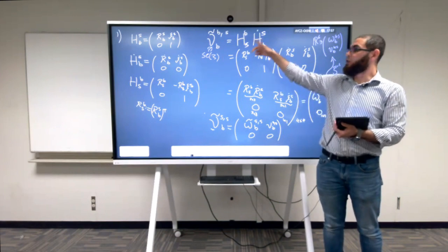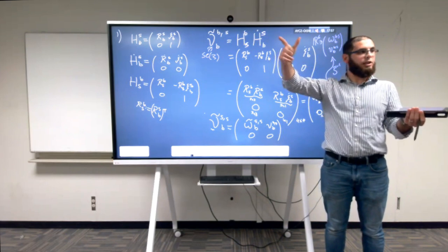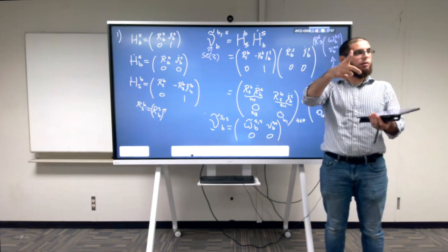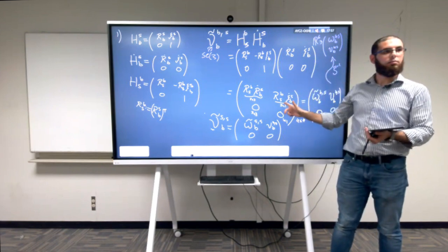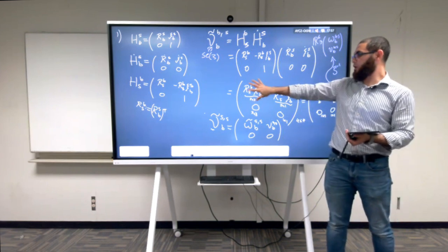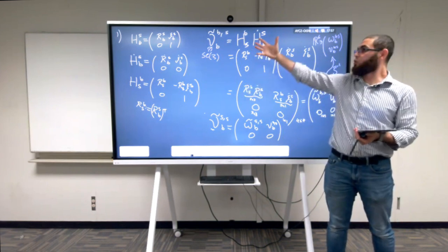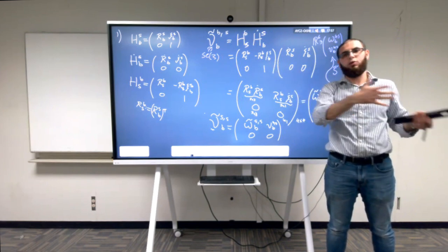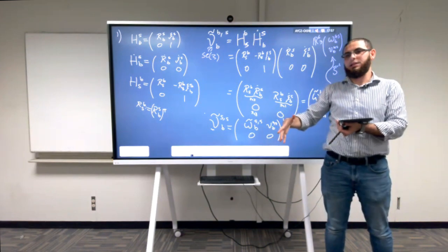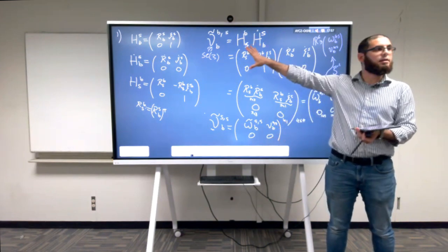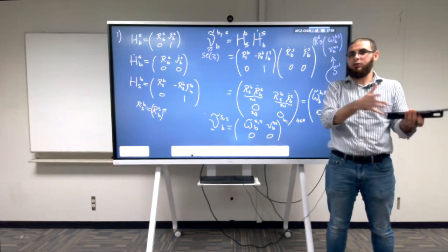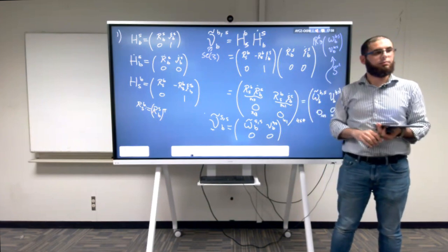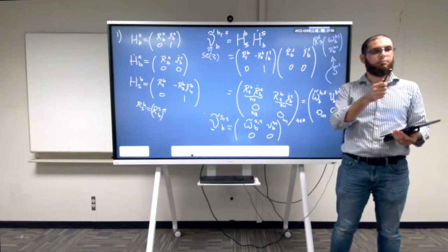If we have a rigid body motion and rotation, in general, and you're not translating, you're just rotating at the same point, then this guy would be zero, and you just recover here what the angular velocity is. And this is why this is the general way of doing it. If you're writing code, you don't think of am I doing translation and am I doing rotation separately? No, there's just one thing given by this. If at some point you're translating and not rotating, it's captured. If you're rotating and not translating, it's also captured. And the math works. Any questions? Okay, let's move on.